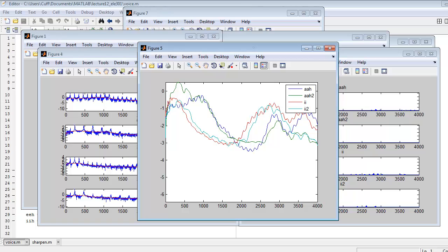Yeah? Like, you can undo the E impulse response, and then do the ah. Exactly, which ends up being a ratio. I just divide the ah frequency response by the E frequency response, and that's the frequency response that I want. So this is on a log scale, so it's the difference between these. I average the green and the blue to get one estimate, average the light blue and the red together, take a difference, take the exponent. So basically I'm taking a ratio, and now I get a frequency response.